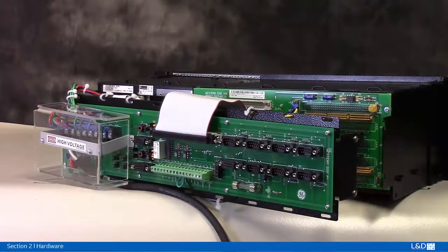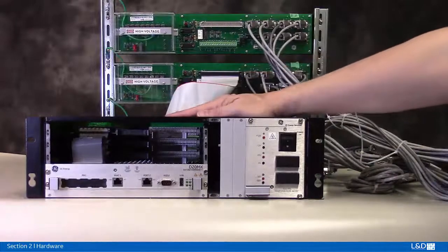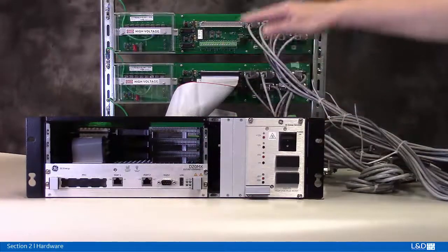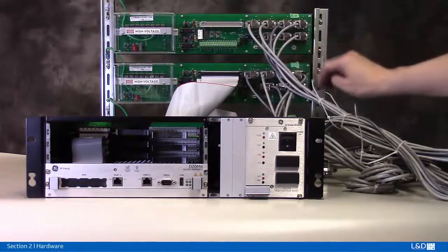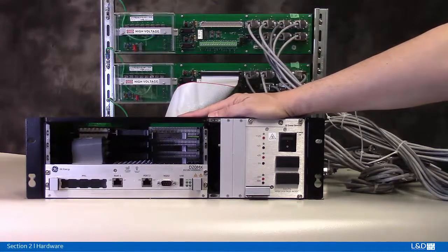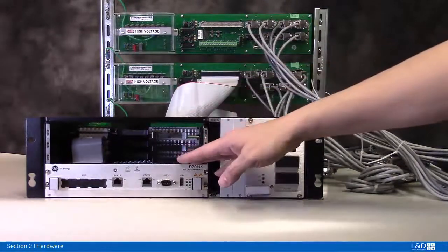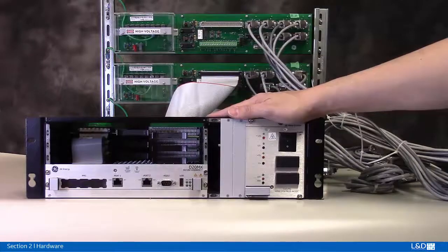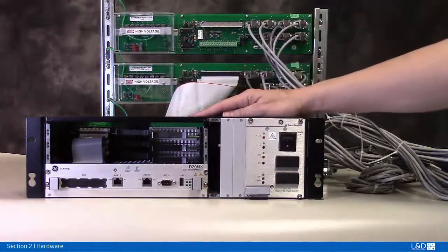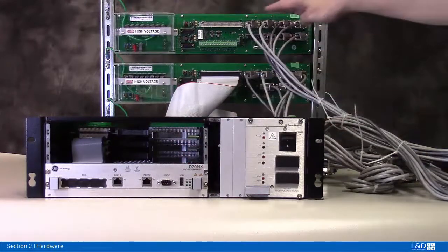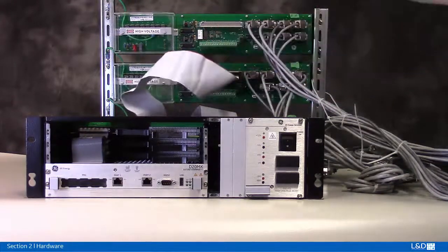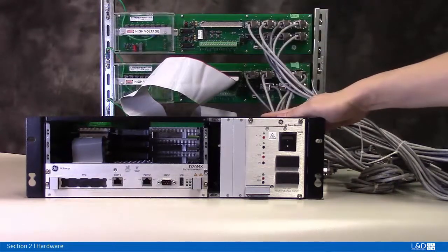single main board chassis. The other D20 MX that you might get from us is the D20 MX with serial expansion cards that will allow you to add more serial ports to your setup. In this case, this is a horizontal D20 MX, and it's equipped with all 3 serial expansion cards. You don't have to have all 3 in here, you could have only 1, 2 or 3 depending on your need. Each one will add an extra 7 serial ports as you see, and each one will connect to a separate ribbon cable to the applicable Westermo card.